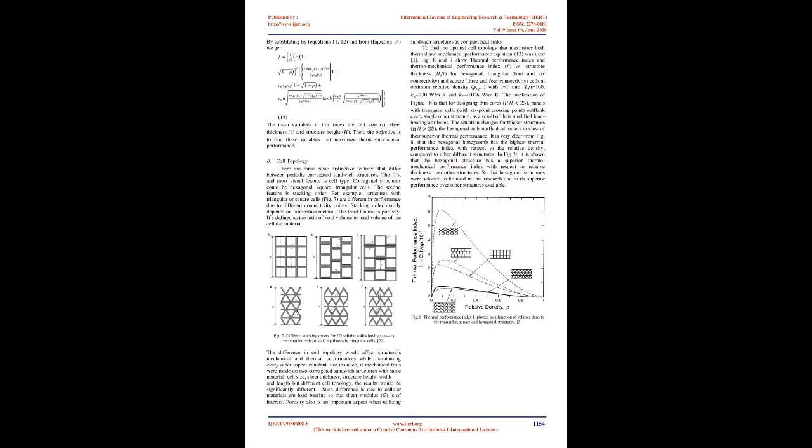In case of laminar flow, the pressure drop across the cellular array derived from the Hagen-Poiseuille solution of the momentum equation is given by the free stream velocity and the cell morphology by equation 14. Where the frictional coefficient equals 14.17, 13.3, 15.07 for square, triangular, and hexagonal cells, respectively. While the effect of cell shape on heat transfer is small, the pressure drop is significantly affected by shape because of the hydraulic diameter.